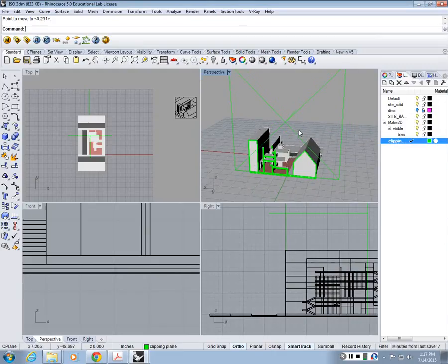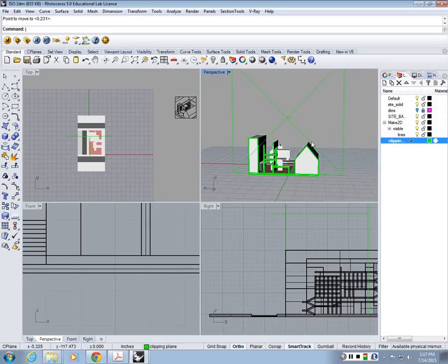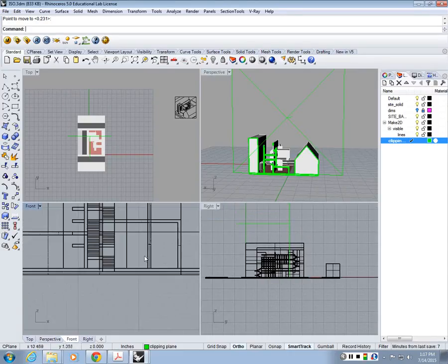They're getting smaller as they are further away from my location. But in parallel projection, everything is the same size and same width. There's no shrinking, there's no vanishing, so everything is projected onto a plane. So it will basically be an orthographic drawing.